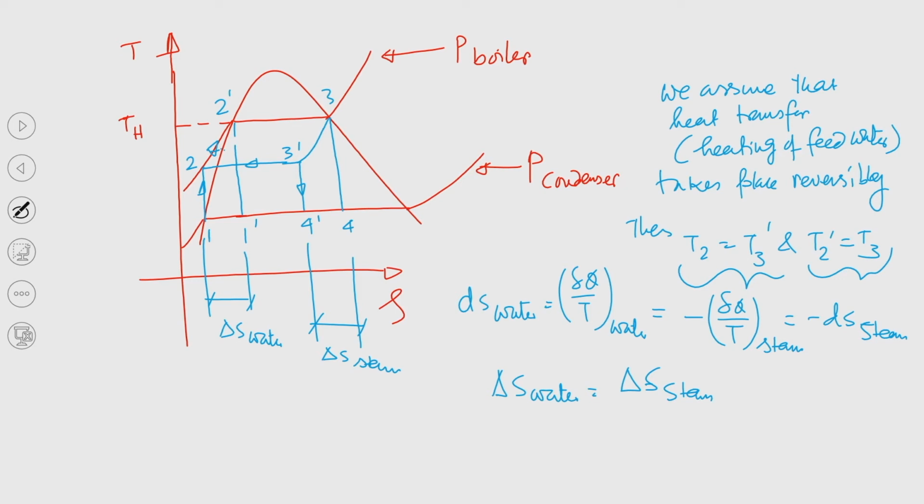right. Say I am giving name, this is A prime, B prime. So, this is possible if we consider the process, this heating and cooling processes are reversible process, right. There is no entropy generation, we can use this expression. So, this is highly for the reversible process, and you can see the minus sign has come only because of the reduction in entropy. But the gain in entropy by water is equal to the loss of entropy by the steam.